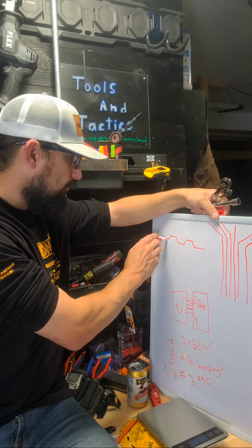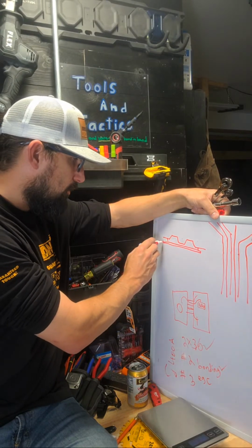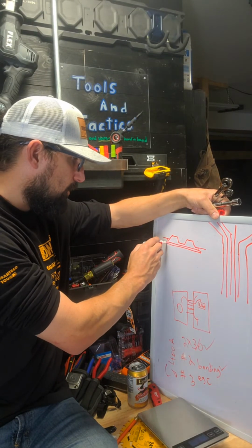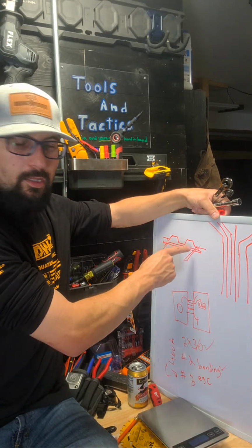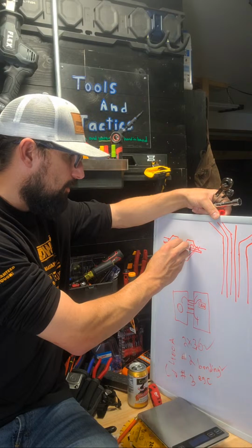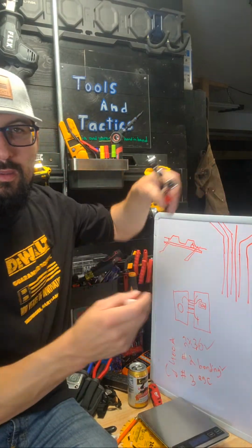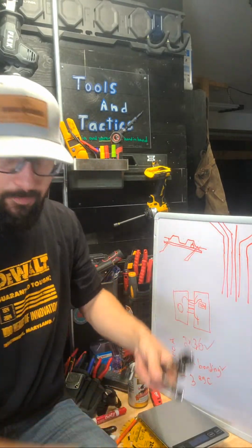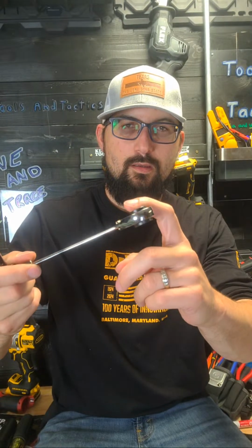And then you'll be running a rack really close up here, and the angle iron might be running this way. So you took your beam clamp and clamped a beam up here somewhere, and that bolt is facing up. You might need a pivotable 9/16 where the box end is able to angle and flex.